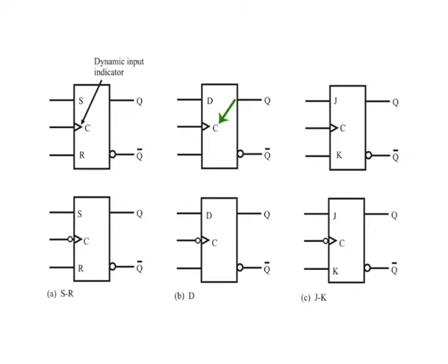Edge-triggered flip-flops. Flip-flops are synchronous bistable devices, also known as bistable multivibrators. In this case, the term synchronous means that the output changes state only at a specified point on the triggering input called the clock, which is designated as a control input, C. That is, changes in the output occur in synchronization with the clock.